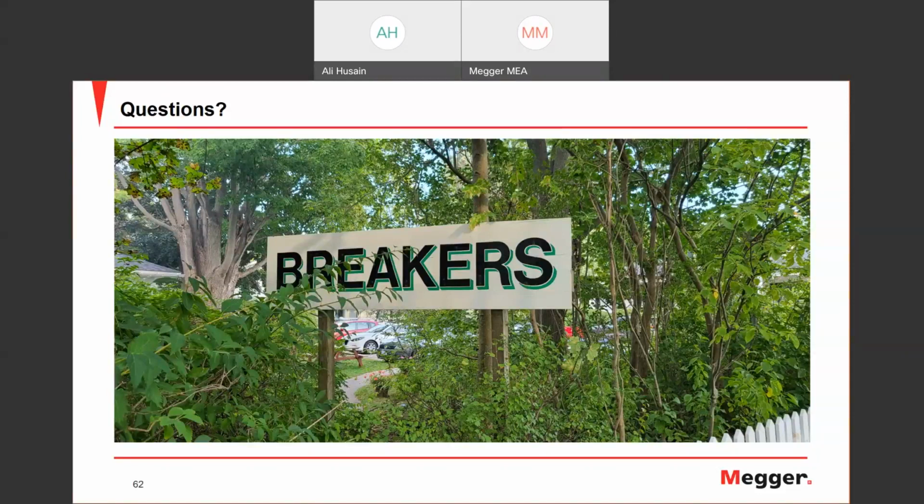You mean like a general test? For circuit breakers, it really depends on the standard followed by the utility or the user as to when to do these tests. Usually, I don't believe it's more than 2 years. A test should be done on these circuit breakers.